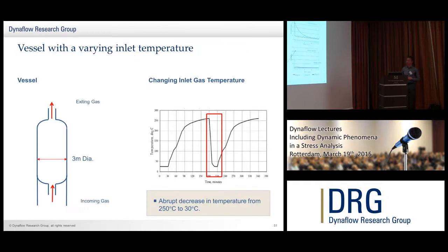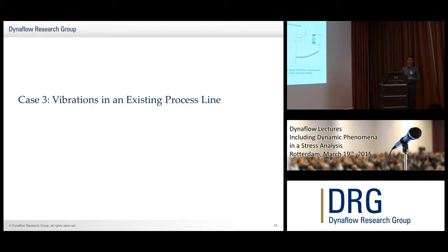We've made the assumption here, well, not assumption, we checked it, that the sharp decrease leads to large temperature gradients within the material. The more gradual increase led to much smaller differences in stress between the two regions, and therefore did not lead to thermal stresses during the heat up. You see this is over 30 minutes, it's based over the best part of an hour.